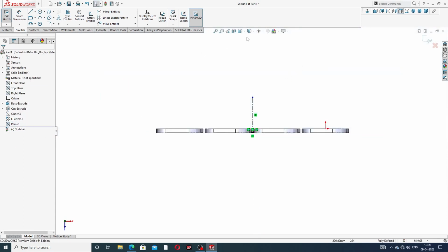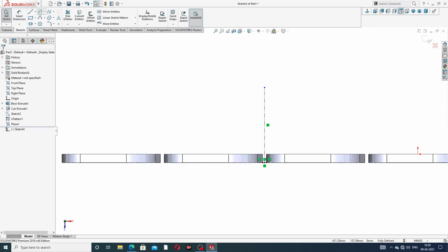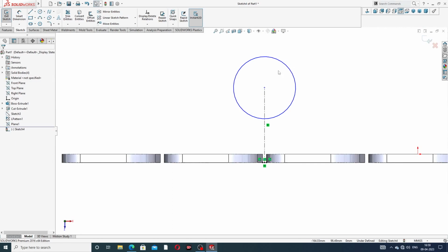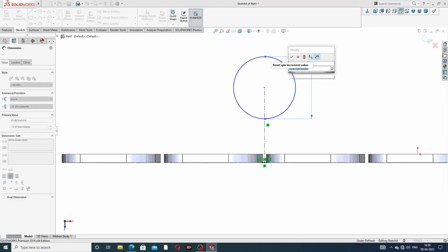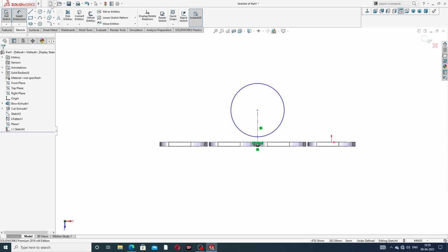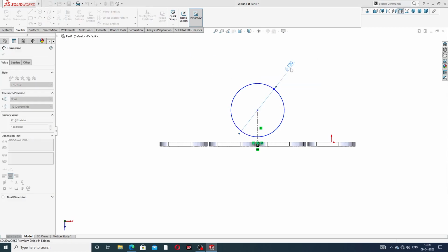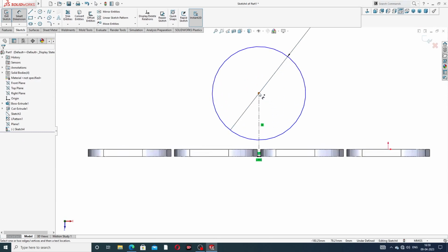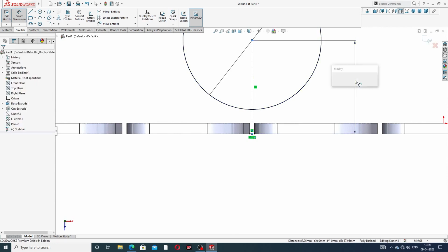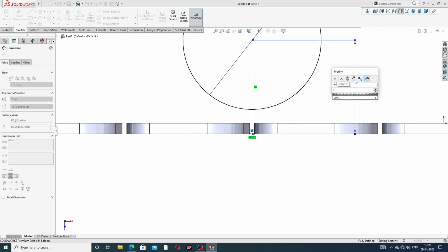because all is looking perfect, and this circle is drawing here this point. Okay, and this circle is drawing here, and this circle diameter is 130 millimeter. Okay, this is delete here and use this is 130 millimeter, and this distance is this to this point distance is 160 millimeter.